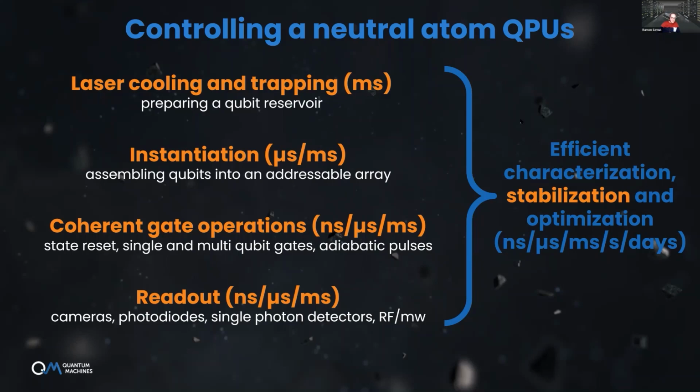You connect it to the camera via USB or Camera Link. You take a picture, you do the image processing in the PC, and then the PC transfers to the pulse processor the array, the occupation matrix. So a Boolean matrix with zeros and ones where there are atoms. And then the pulse processor takes this matrix of ones and zeros and constructs the arrangement waveforms from that.